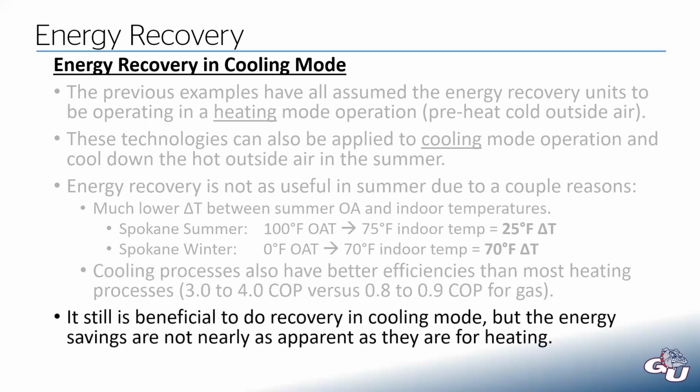It's still beneficial to do it in cooling mode, but the energy savings on that side are just not as apparent. If you already have the energy recovery device installed for heating mode, there's no real reason to not also do it for cooling mode. But it would be a rare occasion that you would install an energy recovery device only for cooling.